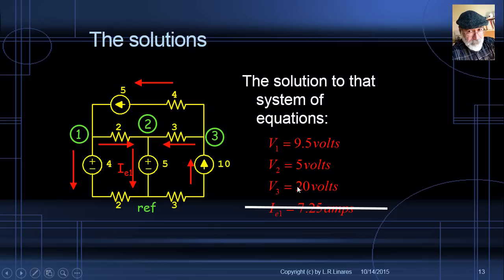We have that data. If in the future we needed the current through this branch, in the middle, the 5 volts V source, well, we compute the 1-2 current, the 3-2 current, use KCL at node number 3, and with that we compute the current I sub E1. Simple, eh? So we realize that an evil branch can be a good thing, a good branch.